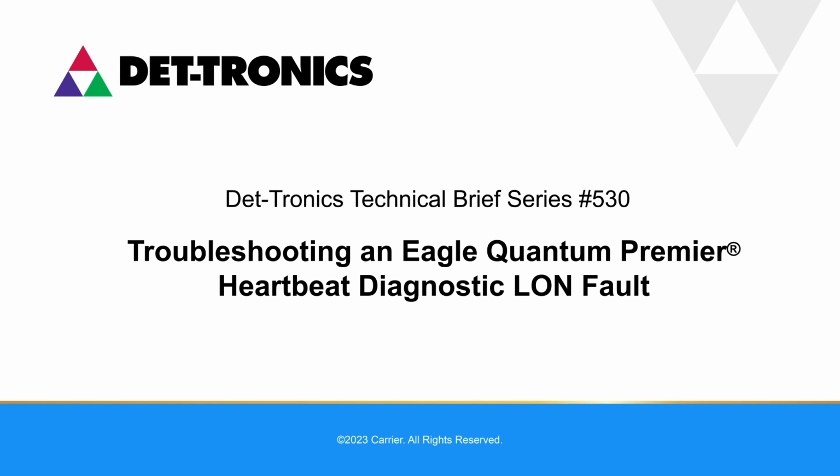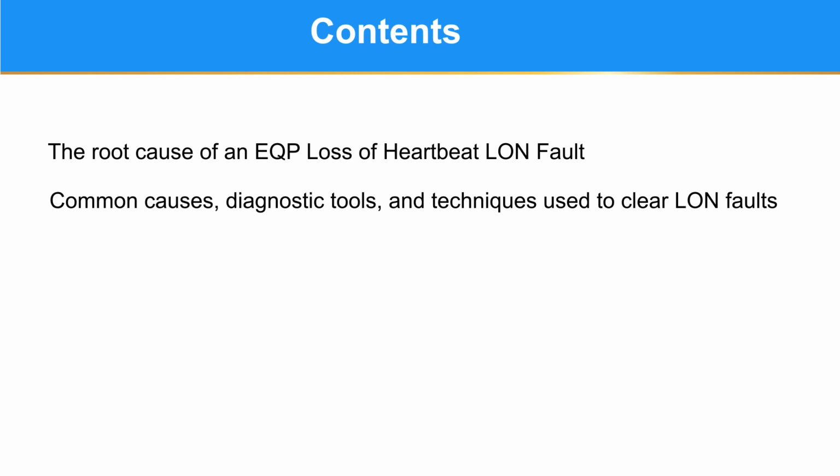Welcome to DET-TRONICS Technical Brief number 530, Troubleshooting an Eagle Quantum Premier or EQP Heartbeat Diagnostic LON Fault. This video will explain the root cause of a loss of heartbeat LON fault, common causes of this LON fault, diagnostic tools, and techniques used to troubleshoot and clear this LON fault.